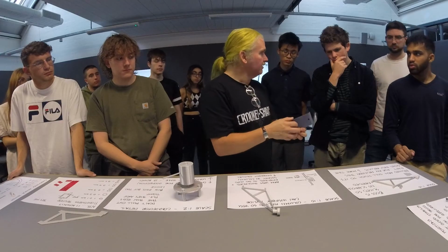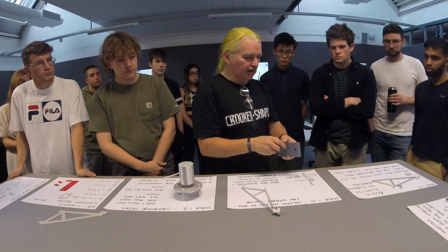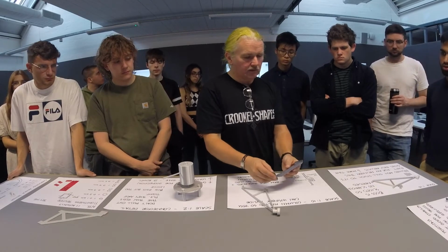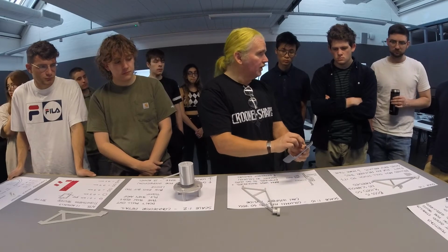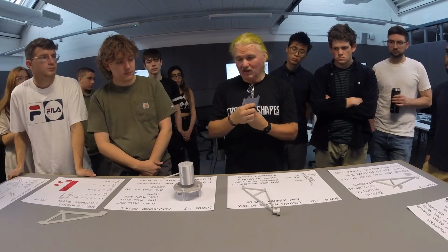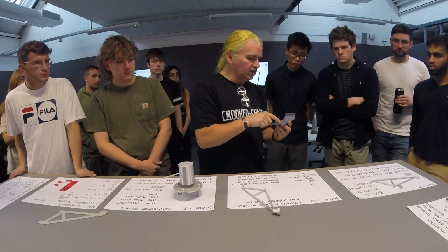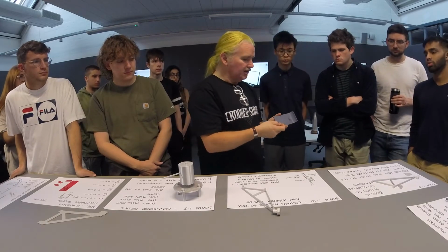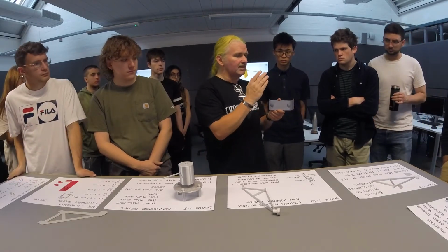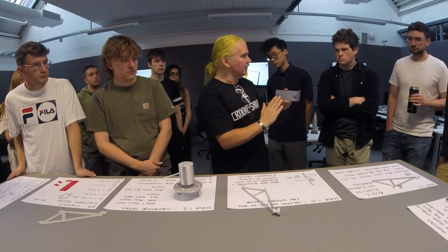The scaffolding comes into play again as well. I 3D printed it like this, and I only did half of it so you could see inside easily. But if we just put a box on the back, there would have needed to be scaffolding below it, all the way to the ground again, so that's more wasted time. So that's where this little slope comes in. If you angle things, and I usually work at less than 40 degrees or steeper, the 3D printer can deal with that.